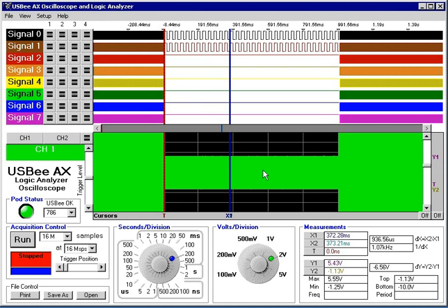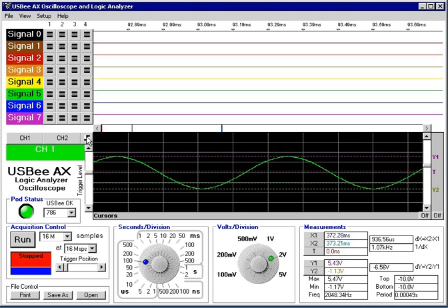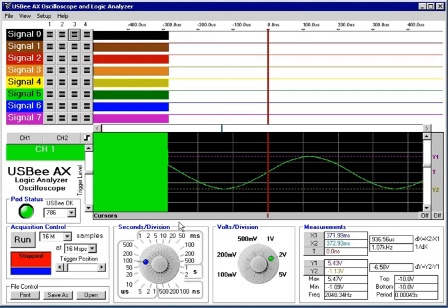The trigger position can be specified either on an analog level or on a combination of the digital levels. For an analog level, if you want to have the position of the trigger occur on the rising edge at a particular voltage level, we will set the voltage level to a particular position, set the rising edge, and when we run the capture, you'll see that the trigger position which is returned comes back and is actually at the rising edge. The falling edge does the same thing. Let's do that.